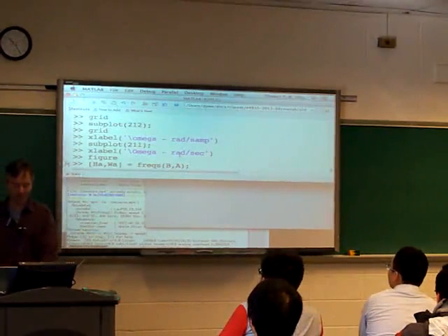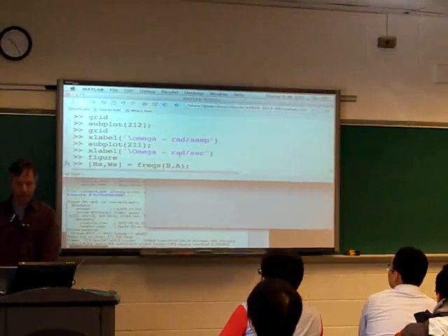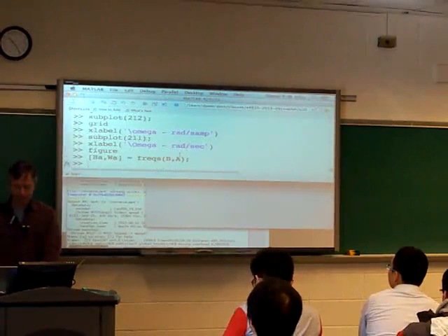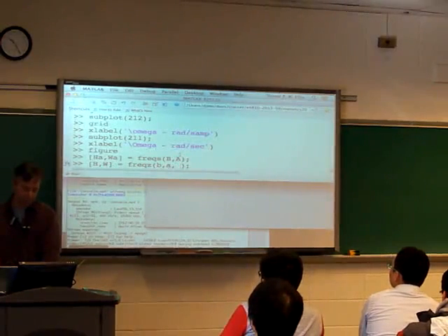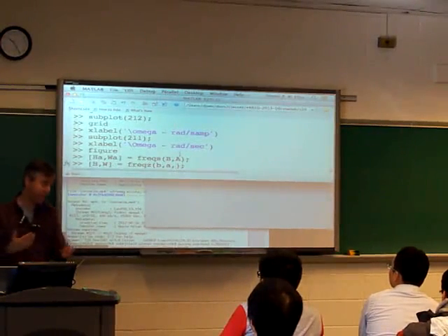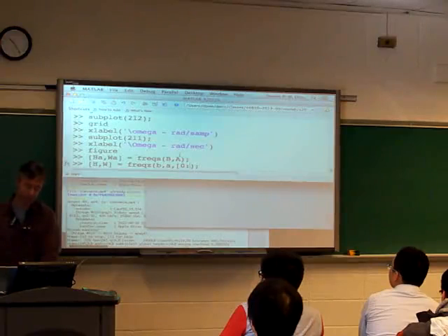We don't really know what it's going to choose. I'm trying to think how to do this. And similarly with freqz, it'll either choose a range of frequencies which is 0 to pi normally, or you can tell it to choose a range of different frequencies. So we could say, go in steps of 0.01 to like 4 pi here.